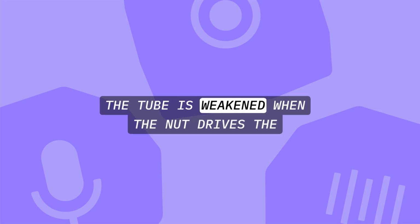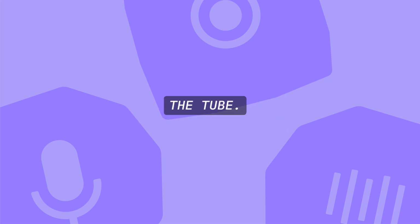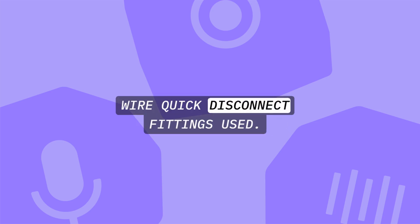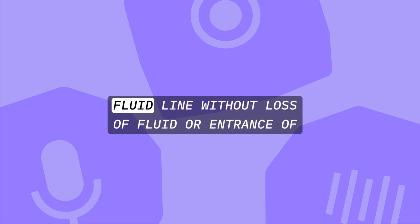What happens to the tube when a flareless fitting is over-tightened? The tube is weakened when the nut drives the cutting edge of the sleeve too deeply into the tube. Why are quick disconnect fittings used? To provide a quick means to connect or disconnect a fluid line without loss of fluid or entrance of air into the system.